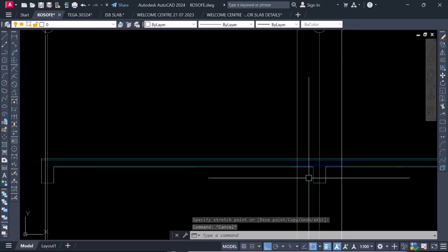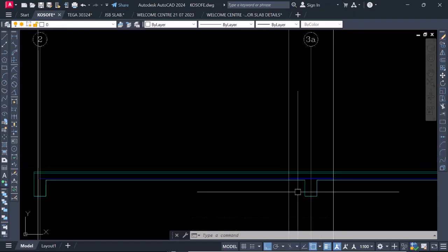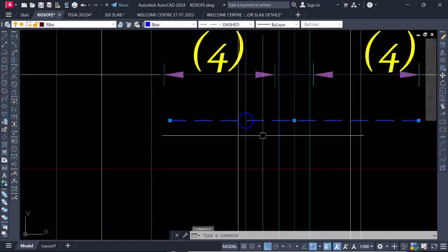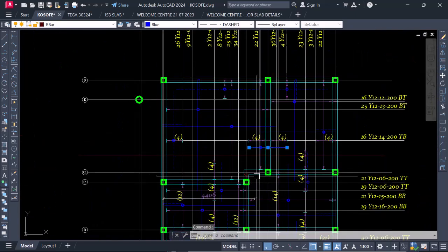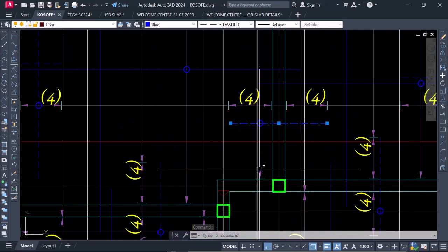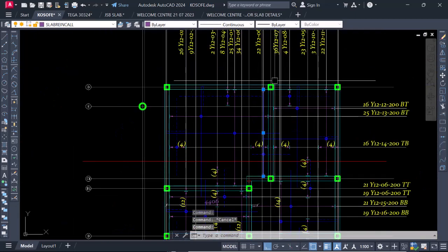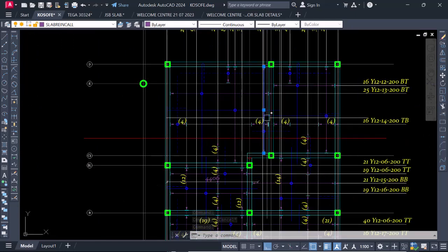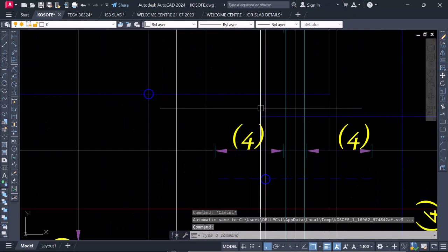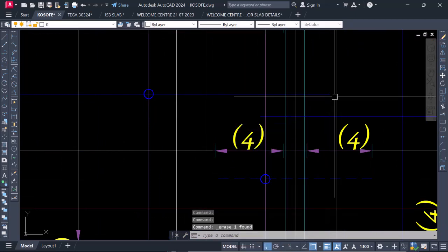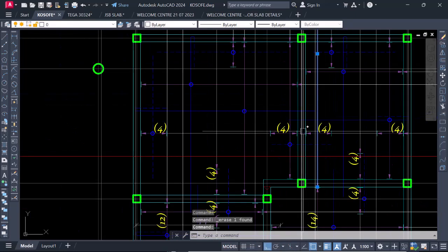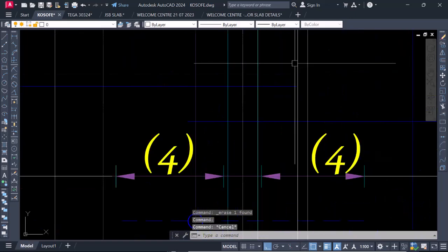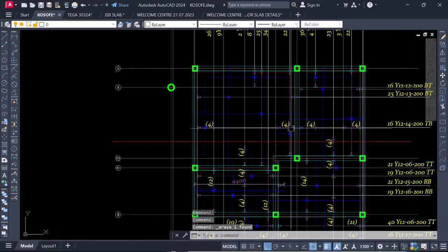Currently, what I'm going to do here is introduce our top rebar, okay? So we're going back to the top rebar. At this top rebar here, what do we have? Here, we have the top rebar running from this axis. You can see the runner, you can see the label line, the call-out line, calling it from this point. Let's take this off because we are done with this. Let's take this also off. Those were done with the bottom bar.